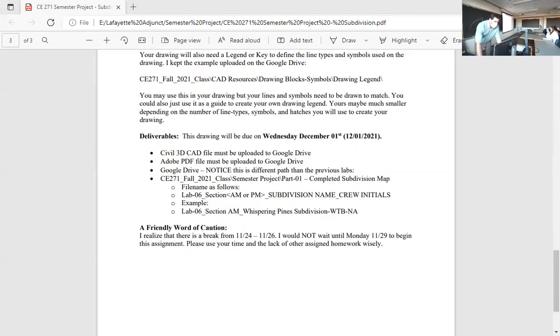All right, so let's get right into the semester project. So I gave you all a paper copy so that you can use a pencil. In ES 101, did you guys learn how to read an engineering scale and lay it down and kind of scale things off of a plan? Okay, so those drawings that I handed out, every inch on that drawing is equal to 50 feet horizontal. So it is a scaled drawing.